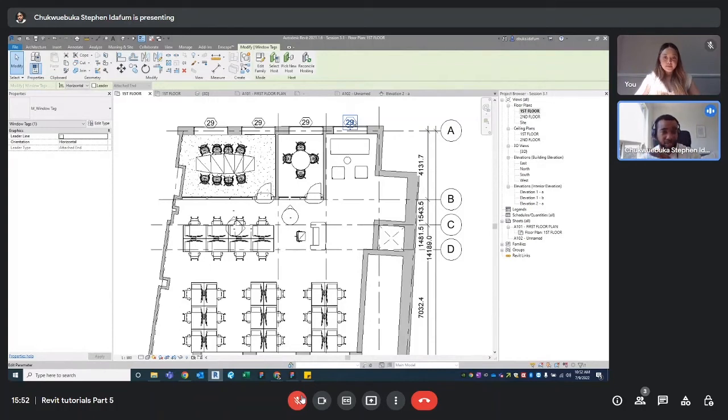Grids, dimensions, partial dimensions, full dimensions, depending on the plans you're putting. If it's a construction plan, it's just showing the exterior walls and the interior walls, no furniture. If it's a furniture plan, it's showing the exterior walls, but with emphasis on the furniture, and you tag the furniture. If it's a finish plan, it's just showing the exterior walls and the finishes of each room, no furniture. So we have different plans that show these different things, organized in different ways.